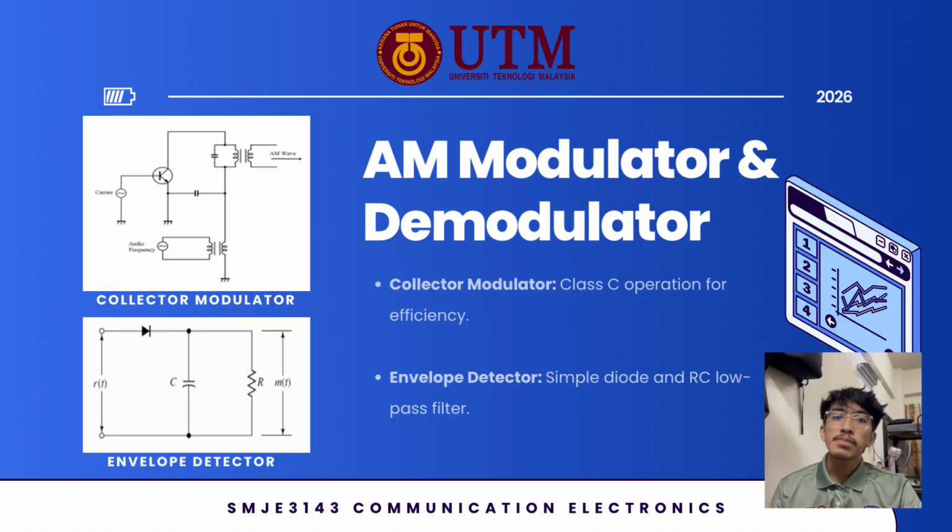To implement AM, I analyzed the collector modulator. It utilizes a transistor operating as a Class C amplifier, where the collector supply voltage is modulated by the message signal. For the demodulation process, we use an envelope detector. This circuit is highly efficient and cost-effective as it only requires a single diode for rectification and an RC low-pass filter to remove high-frequency components, leaving only the original message signal for the user.